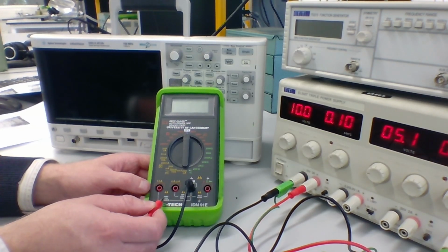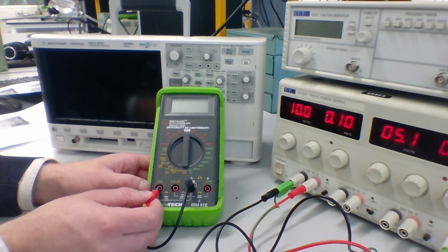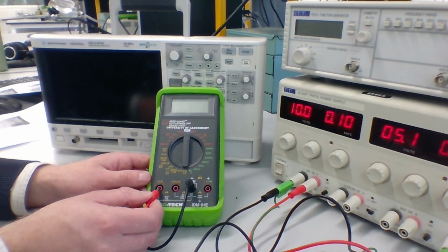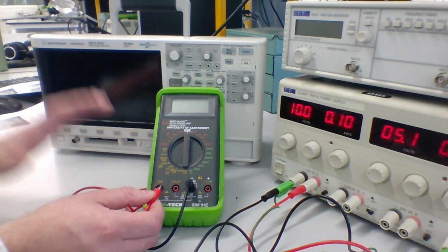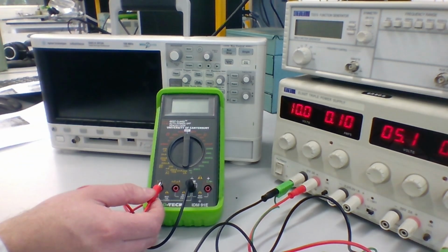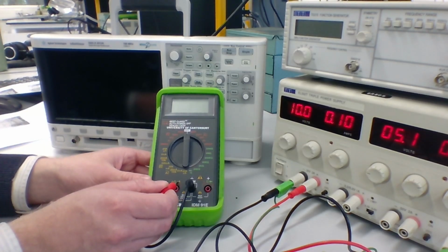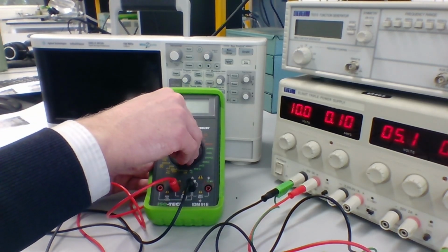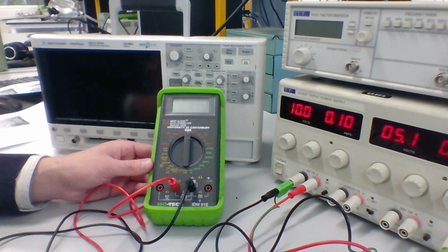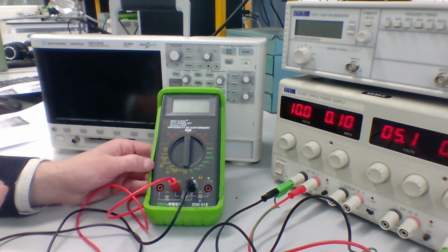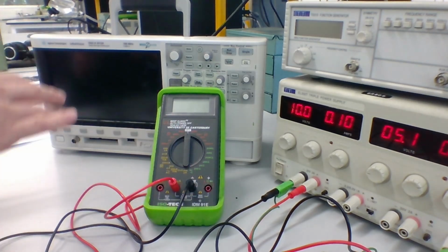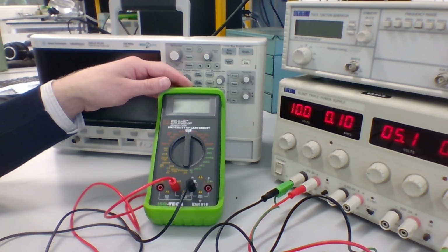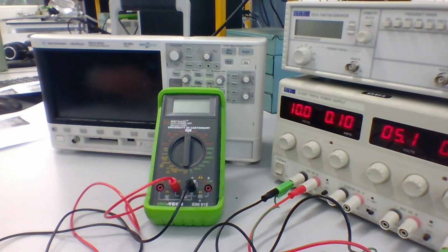The other current measuring port has a 10 amp fuse on it, so you can use that to measure larger currents. Note that some multimeters may have this larger one unfused, so just be a little bit careful, check what fuse exists if any, and be careful what currents you're measuring. So I'm going to plug that into the current port there. Now if I switch to measuring a voltage, the multimeter will beep at me, warning that I have set this up to measure current, but I've turned the multimeter to measure voltage. If I try and do that, I'm probably going to just damage or destroy the multimeter. So just a little warning to you there.